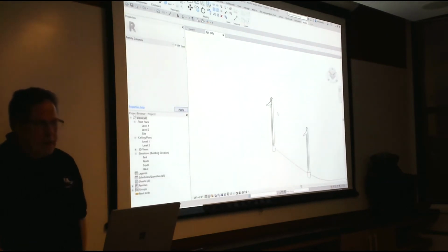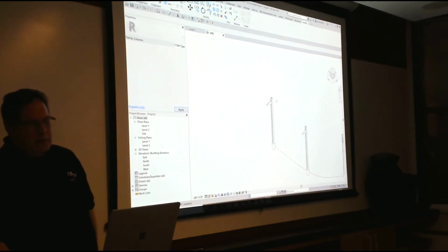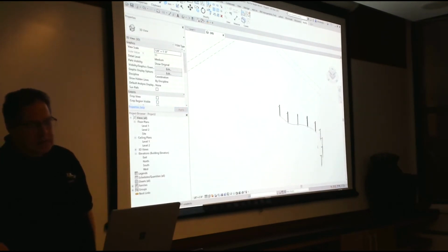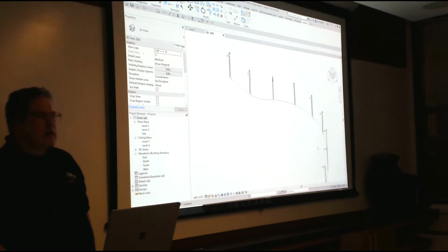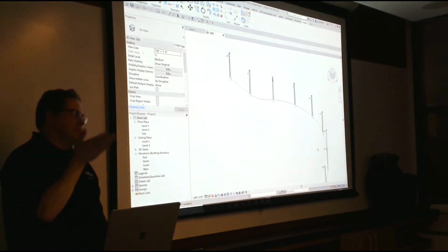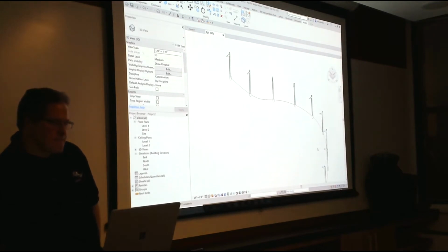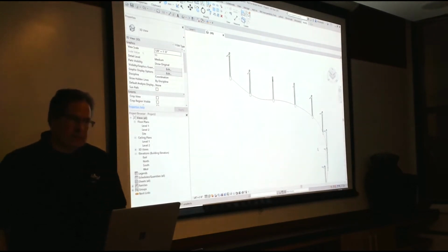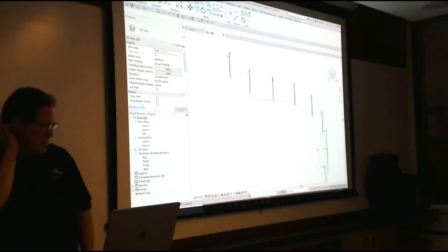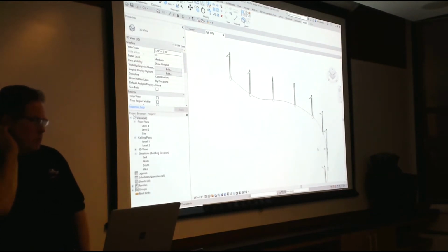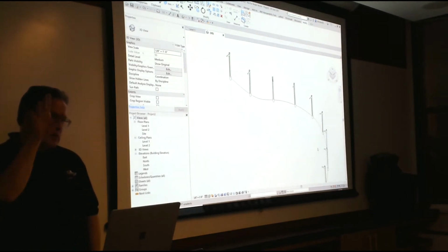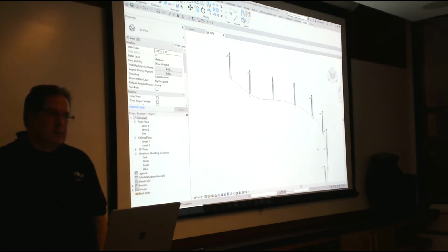All right? But what I have here, if you take the time to wrap all your objects in families, then somebody downstream will be able to make sure it cuts, hatches, and sections properly. So it's worth the extra effort. This is not an in-place family, but it's an embedded project family. You can write it out as an external family too if you want to, with Grasshopper. So does that help a little bit?